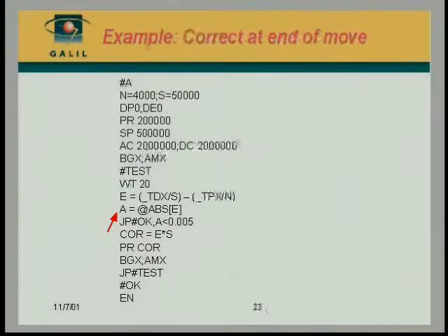If on the other hand we find out that it's not, then all we have to do is make a correction. The correction magnitude is equal to E in revolutions multiplied by S, the resolution of the stepper. So this would be a certain number of pulses, for example, 723 pulses. Then we command the motor to perform an additional move, position relative of correction, begin that, and at the end of the motion, if we're still not certain, we could go through the test routine again and make sure that the correction succeeded. We could theoretically do that a few times until the motor ended up at the right place.